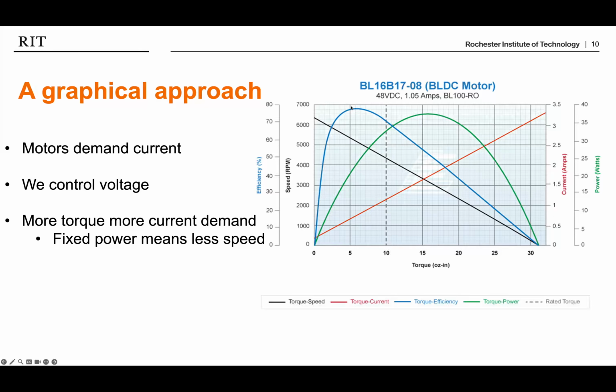We have this peak efficiency that's at a much lower torque, and then after this max efficiency, we start to taper down, and then we pretty much linearly drop off to a point where we have no efficiency because we're not moving. We might have a lot of torque, but we have no motion, which means we're converting pretty much everything to just heat at this point.